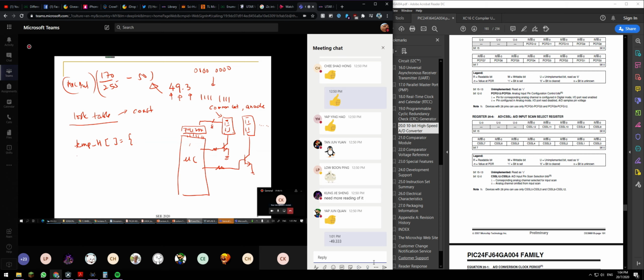So you can have a temperature high, temperature low. Let's say, how do I do it? This is all my display pattern. Let's say 0x74 is display negative, 0x30 is display 0, example like this. So here I can put all my possible outputs for my analog digital converter.